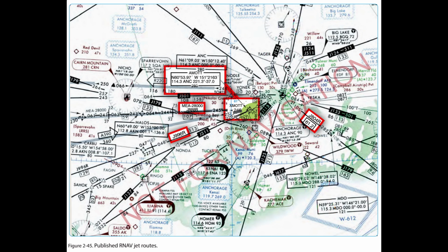6. Record latitude/longitude coordinates by 4 figures describing latitude in degrees and minutes followed by a solidus and 5 figures describing longitude in degrees and minutes. 7. File at FL 390 or above for the random RNAV portion of the flight. 8. Fly all routes/route segments on Great Circle tracks. 9. Make any in-flight requests for random RNAV clearances or route amendments to an en route ATC facility.